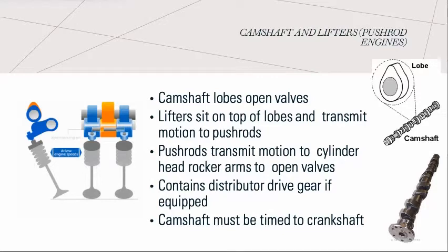operating of the engine. So-called cam-in-block engines use push rods to transfer the camshaft lifting motion to the valve by way of a rocker arm on top of the cylinder head. The tappets or lifters ride right on the camshaft lobes to actuate the push rod, rocker arms, and the valve. The timing of the camshaft is all operated through the cam belt or timing belt, which is synchronized with the